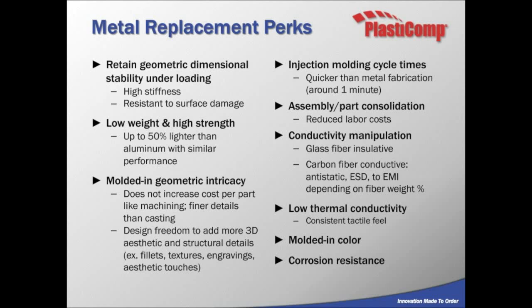And that conductivity manipulation, if you're dealing with carbon fiber, depending on the amount of loading you're using, you're manipulating the electrical conductivity of the part. And that has really useful ramifications when it comes to the EMI market and trying to electrically shield your product from whatever EMI waves are coming in from the surrounding electrical products. So that's a good one to keep in mind as well.